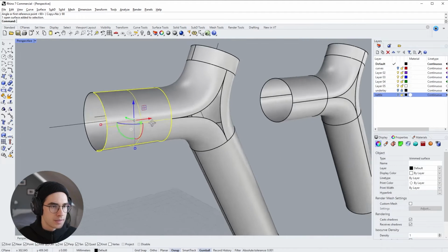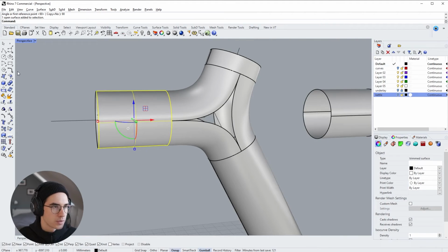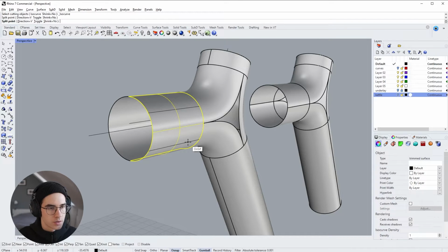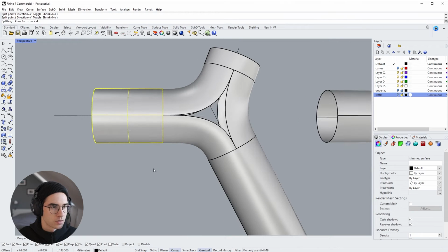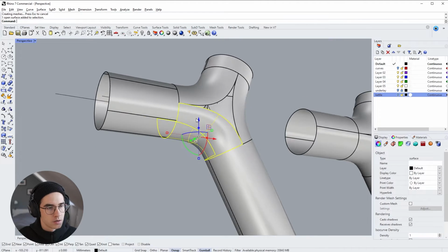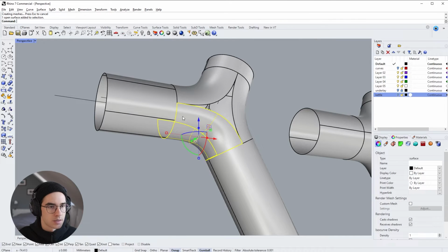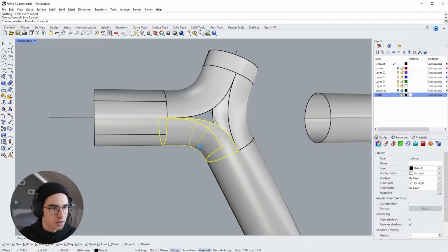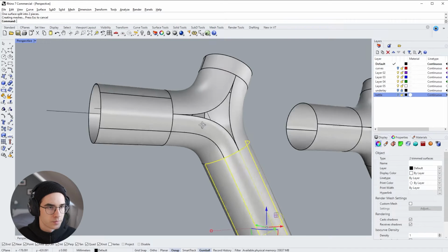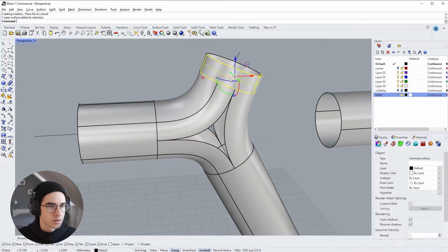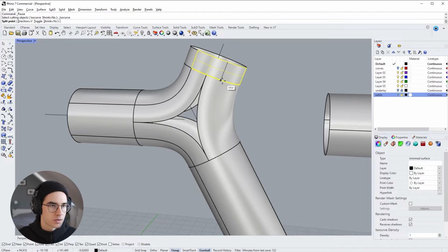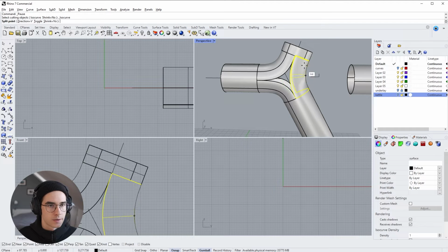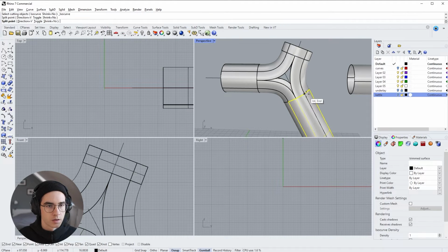Next, we want to split this half in two elements. So right click on the split surface and then split it somewhere arbitrary between those halves. I think this should be fine. And then do the same thing along the line. So split this blend again at the same point, right click, and this one as well. Then go up here, split this one and this one. And then here we need to have a new split. So as well here, let's uncheck center, somewhere here, enter, and then again at the same point along the right.